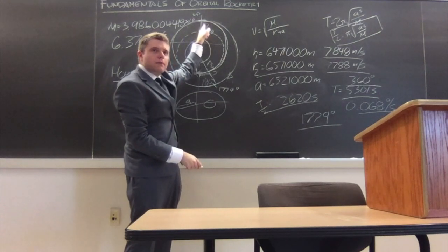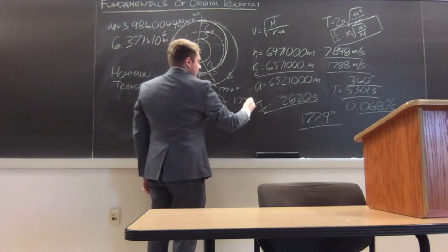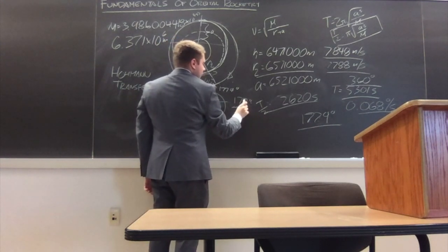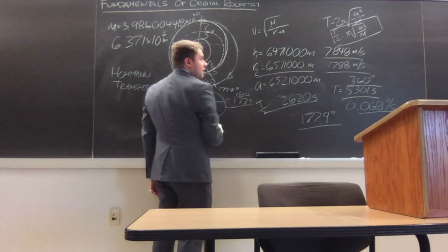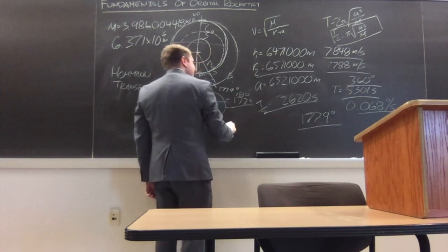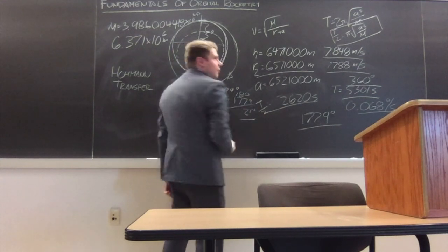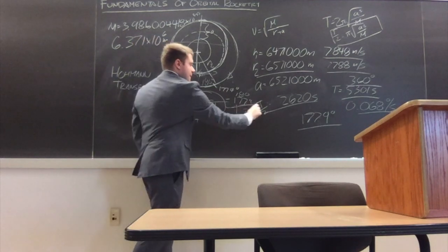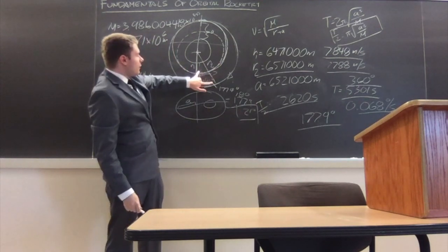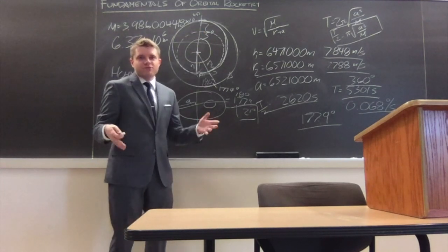How many degrees ahead of us is it? Well, that would just be 177.9 minus 180. Well, 180 minus that, I'm sorry. Math ain't my strong suit. Kind of ironic, isn't it? So that's about 2.1 degrees. So once the vehicle is 2.1 degrees ahead of us, we make our burn and we'll meet it at apoapsis with some error here or there.